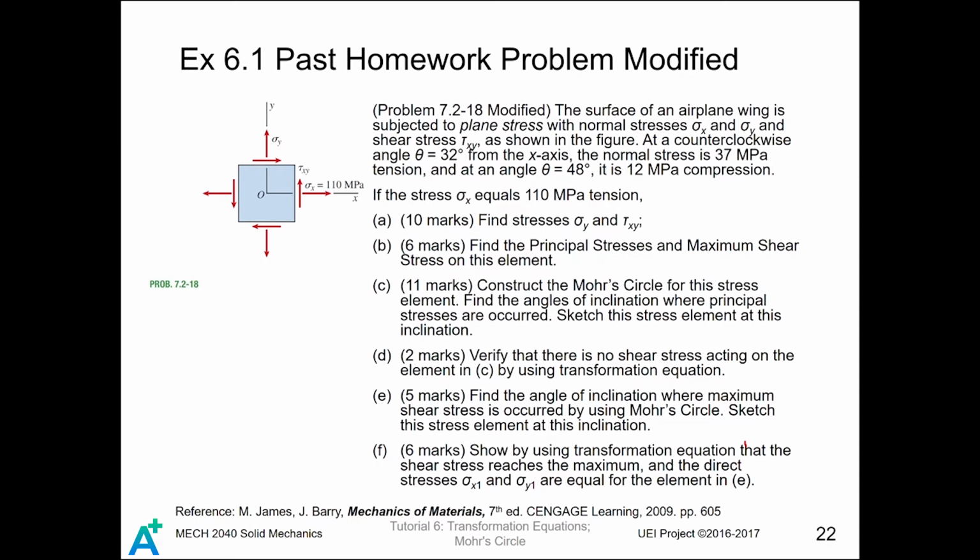Besides, I want to construct the Mohr circle for the stress element and find the angle of inclination where the principal stresses occur. You're also going to sketch the stress element. At the same time, you are going to verify there is no shear stress acting on the element by using the transformation equation when the principal stresses occur.